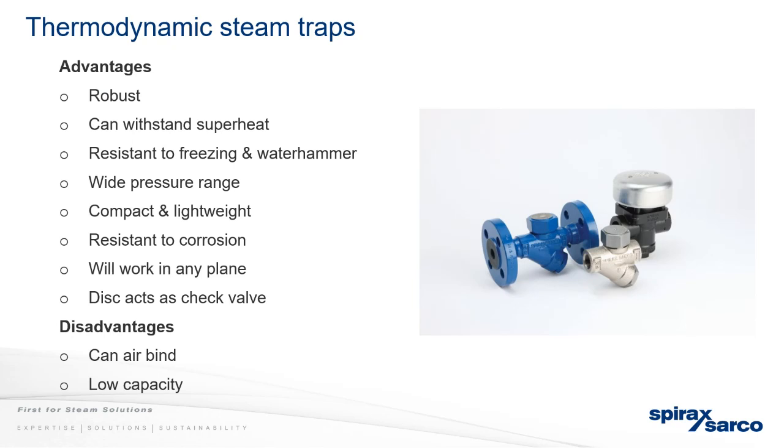So you want to remove as much air as possible so that you can maintain the temperature you require for cooking or for process, but also so the transfer of heat is more efficient. There's no barrier in there. You also have the added issue that when air binds with condensate, you get carbonic acid, so then you have more corrosion and erosion in your system. Hopefully that covers that part.